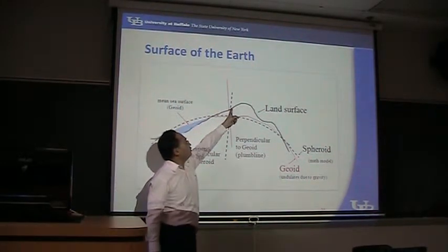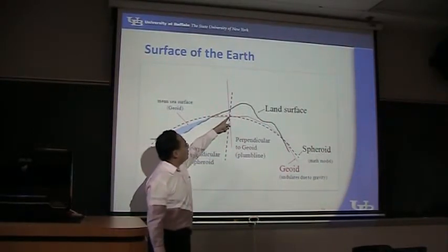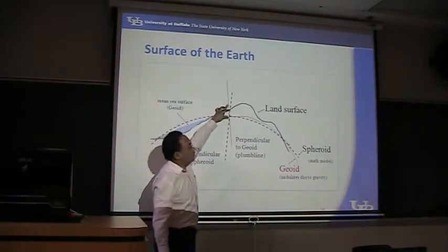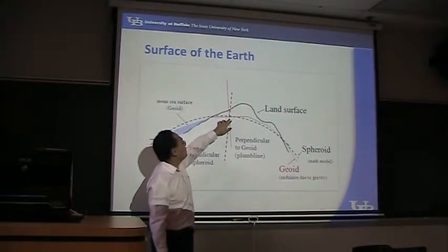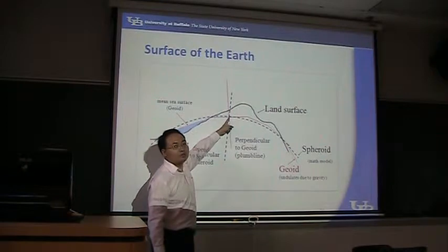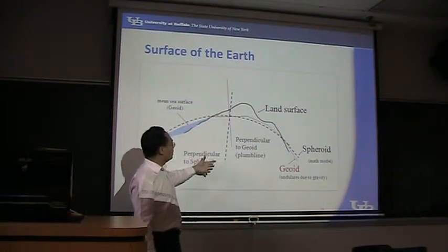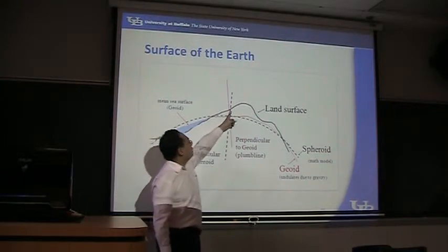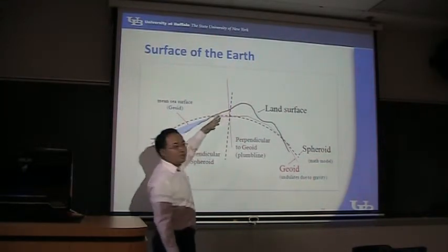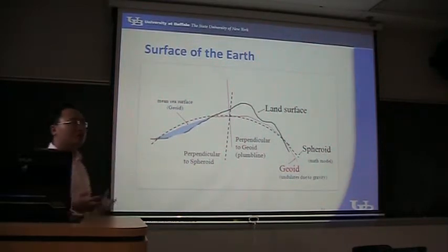This place on the hill. If we use the spheroid model, you will have an elevation, and you will have a longitude and latitude that's the same to this point, base point. But if we use the geoid, or the mean sea level, it must be projected to another place. So it has different longitude and latitude, and you will have different elevation.